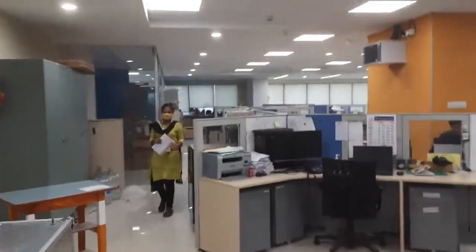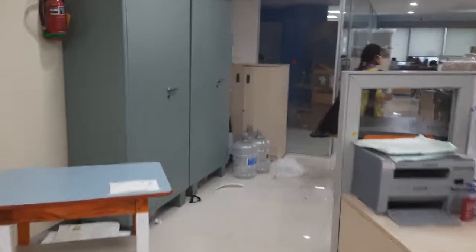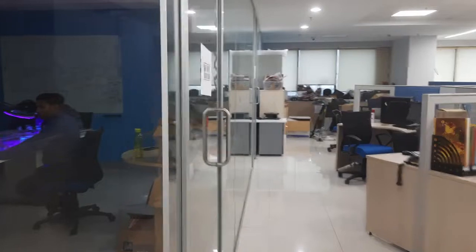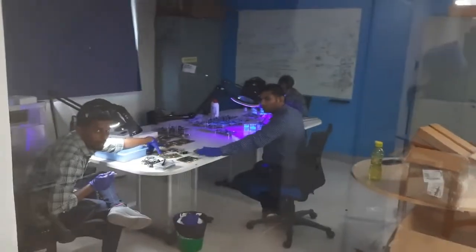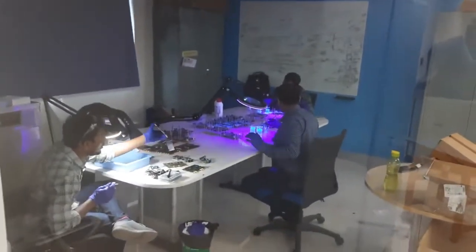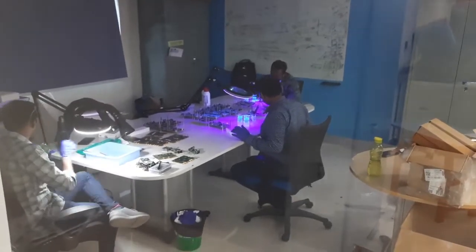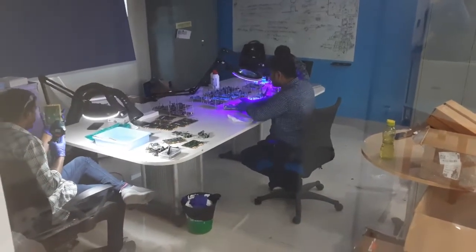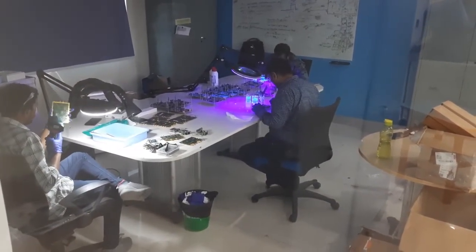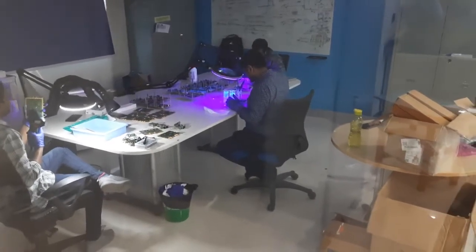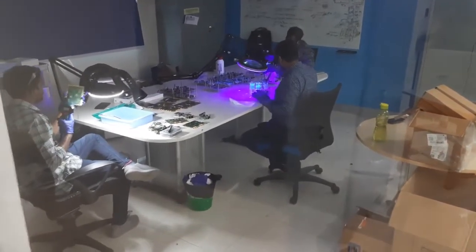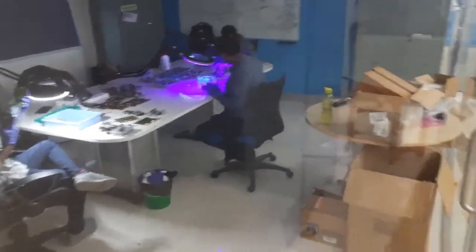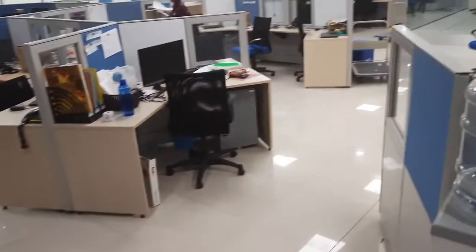Further, one of the important steps in military system qualification is to ensure that the system qualifies the environmental conditions like high humidity. So a special coating will happen. As you can see, once the PCB is assembled and before it goes to integration, they apply this conformal coating, by which it becomes resistant against humidity variations and atmospheric variations.